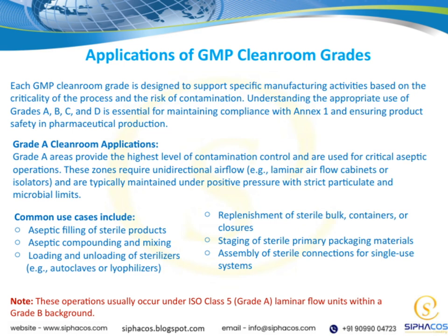The key activities include replenishing sterile bulk materials, containers, or closures, staging sterile primary packaging components, and assembling sterile connections for single-use systems. Common use cases for these environments are critical, including aseptic filling of sterile products, aseptic compounding and mixing, and loading or unloading sterilizers like autoclaves or lyophilizers.